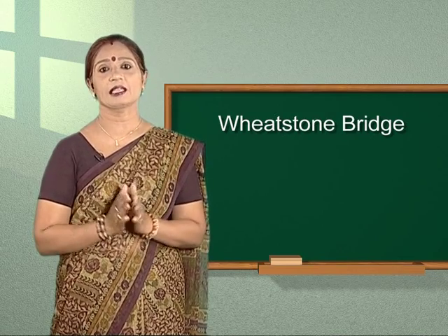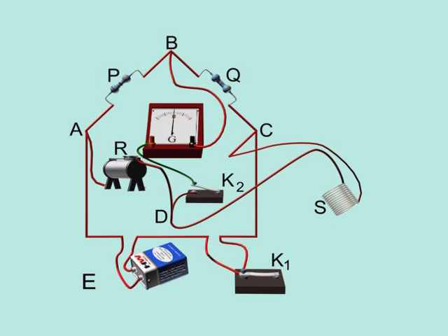I will teach you how to calculate its temperature. We will take a platinum wire about 50 centimeter in length and wind it on a non-conducting rod with non-inductive winding. Connect this platinum wire in the arm CD of Wheatstone bridge circuit. Make the connections as this diagram shows. Let me first tell you the working and then explain the theory behind this working.